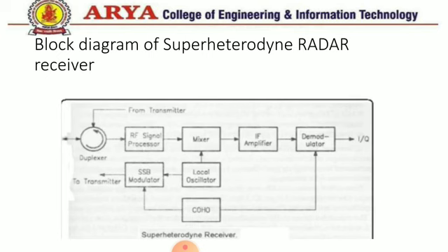It is used for improving the signal to noise ratio of the system. So the IF amplifier in a radar receiver is designed to perform the same function as a matched filter. Further, the signal is given to the demodulator so that the signal is demodulated and the original data is available to the user. That means the range or the position is available to the user.